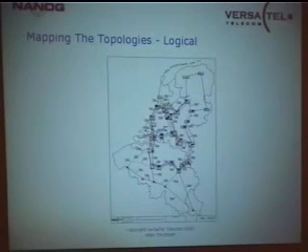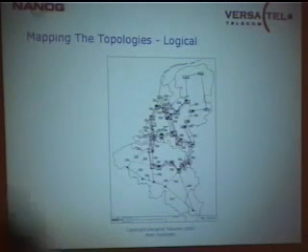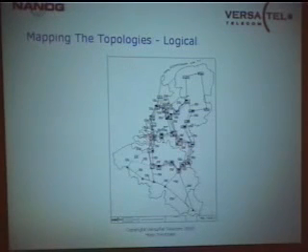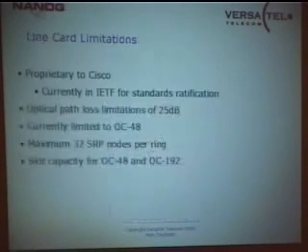Unfortunately, this didn't come out as well, but this outlays optical path loss on the network as well as where we've decided to place the regenerators. In some places, we've chosen to build a POP, a point of presence, where we need to optically regenerate. In other places, we've decided to splice the fibre, cut the fibre open, and put the optical regen in. It's a shame this slide didn't come out more, because I wanted to cover some more issues, but I'll come back to these a little later.